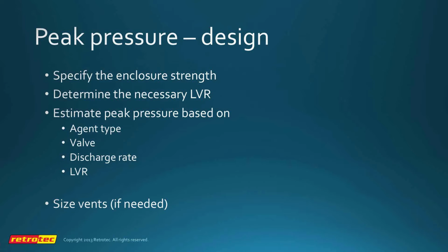Then we need to determine the necessary leak to volume ratio, and then to estimate the peak pressure based on agent type, valve discharge, and the leak to volume ratio, and then to size vents if needed. Now, for ISO, you can forget about the if needed.